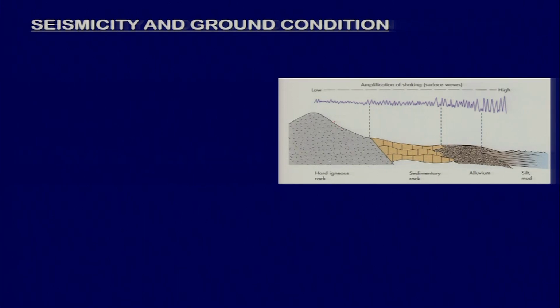So if you consider this as the Himalayas and this as the Indo-Gangetic plain, one can easily understand that this area is going to be affected more, because the amplification will be much higher. Ground shaking will be much higher as compared to what we will see in the hard rocks. Of course, the Himalaya does not consist purely of hard rock; it also has fluvial and marine deposits. So we will face something like what we see in the sedimentary rocks.